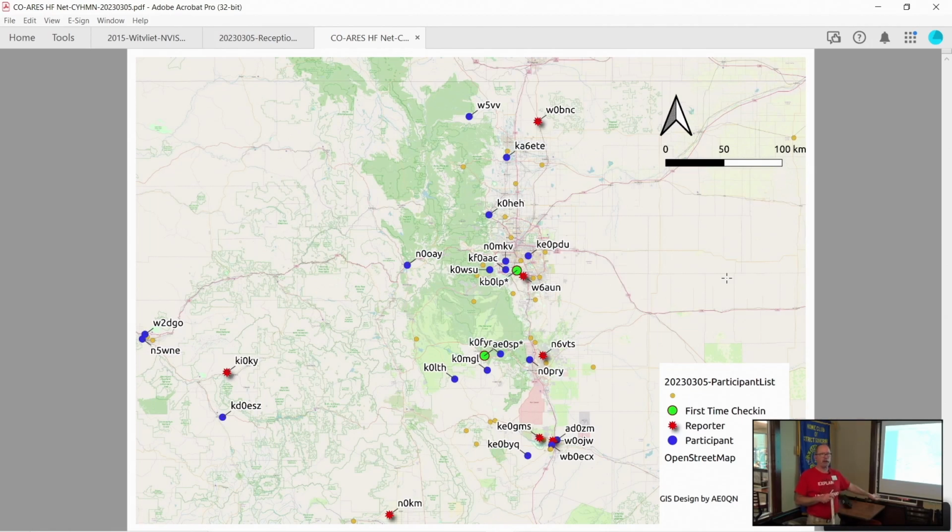Some people play around with putting reflecting wires on the ground underneath. I haven't really played with that, but from what I've read, if you're up 15 feet or more, that's not as critical. As you get down close to the ground, it becomes more important to have a reflecting screen on the ground to prevent RF loss into the dirt. And the other thing it will do is give you more consistent SWR as dirt conditions change: wet, dry, snow, frozen, thawed. So you'll remove some of that variability.